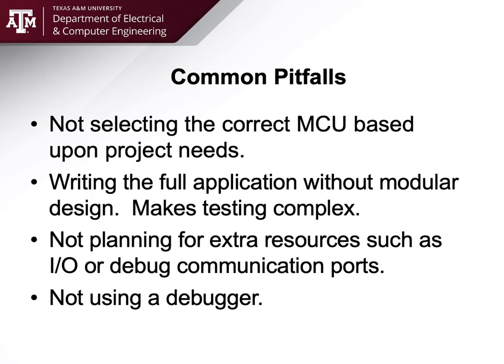Not using a debugger. Again, at the hard embedded level, at the microcontroller level, if you're not using a debugger, and you have one available for you, you're being a little bit foolish. Debuggers are fantastic devices. They'll let you stop and look at variables while the code is executing. So it gives you a snapshot of what exactly is going on at the embedded level.